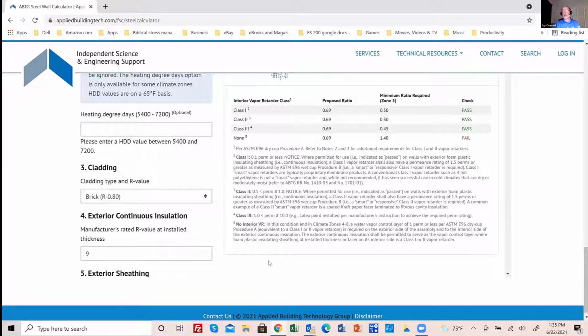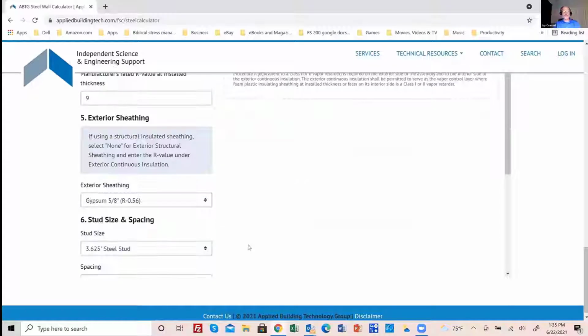retarder. And in that application, the foam sheathing can serve as your exterior vapor control layer, as well as your insulation layer, and as we'll look at shortly, your water resistant barrier layer, as well as your air barrier layer if you want to. Or you could combine other materials to have some of those functions. It's really up to how you want to specify the wall, but foam sheathing would allow all of those functions to be handled with the one product.